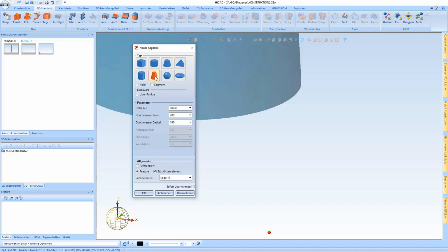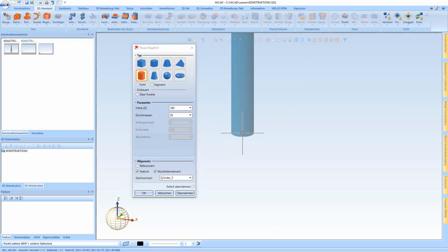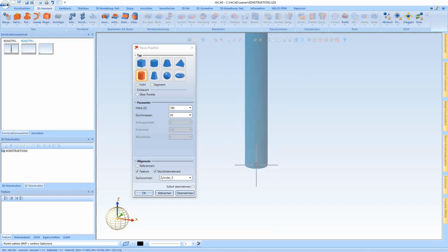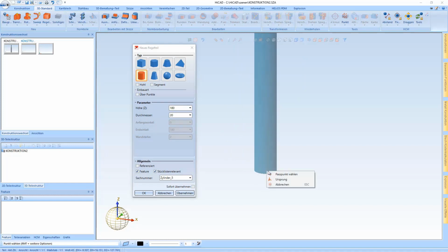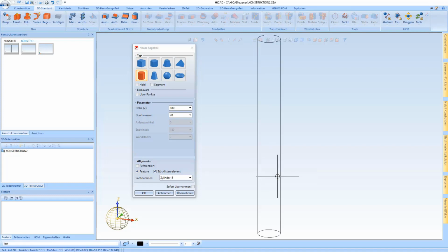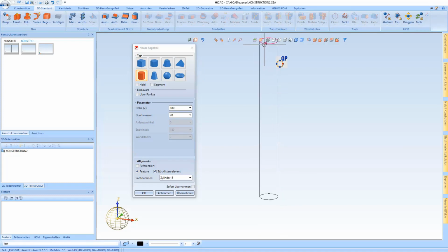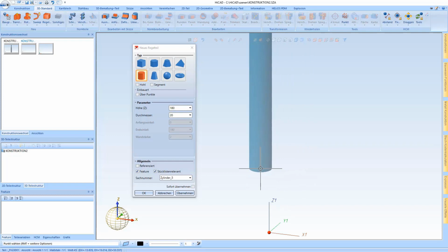If we click on a solid primitive icon, for example the cone, we also see that the according entry fields are described in more detail. Also, via a right mouse click, the fitting point can be changed. This is the point placed above the solid primitives in particular. For instance, we could select a quad point, the center of the top surface or bottom surface.